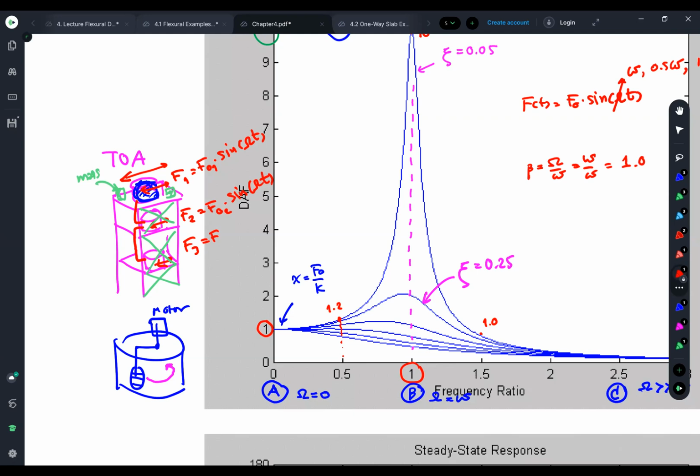If I understand you correctly, you try to change the directions of the motor. You said something about clockwise and counterclockwise on the first machine, the second machine, and the third machine. That's a very good and very smart idea. I also share the same opinion as you to the manager of this manufacturer. Just change the phase.